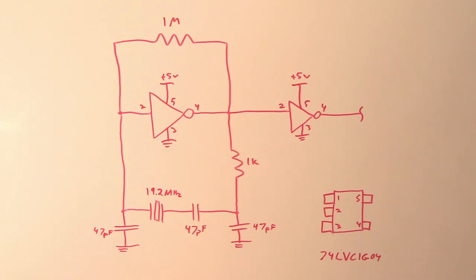Now I need to build a 19.2 megahertz oscillator, and I of course have some 19.2 megahertz crystals, and I'd like to use them in a Pierce gate oscillator configuration. But before I commit to this topology, I really want to evaluate A, whether I'm going to have sufficient gain margin for this oscillator to start up reliably, and B, to make sure that I'm providing a good loaded Q for the crystal, because crystals have very high Qs, but when you stick them in the circuit it's going to degrade their Q. So you really want to make sure that you keep that loaded Q when the crystal is inserted into the circuit high in order to maximize stability.